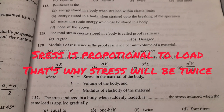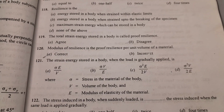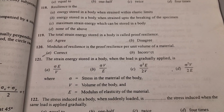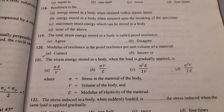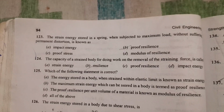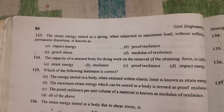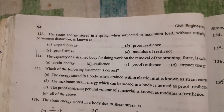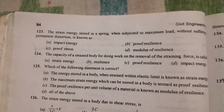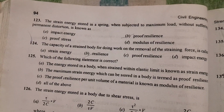So the stress will automatically be twice for the body subjected to suddenly applied load as compared to the body subjected to gradually applied load. So option C is the correct answer for this question. Next question 123. The strain energy stored in a spring when subjected to maximum load without suffering permanent distortion is known as, option B is the correct answer, proof resilience.